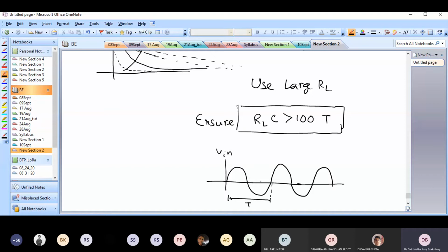So basically the signal fluctuates fast, but my RLC circuit discharges very slowly with respect to these fluctuations. So that's how I can say that my circuit will hold on to that Vp voltage for a long time, for several fluctuations of the input signal. And that makes me get an approximately constant offset voltage of Vp.